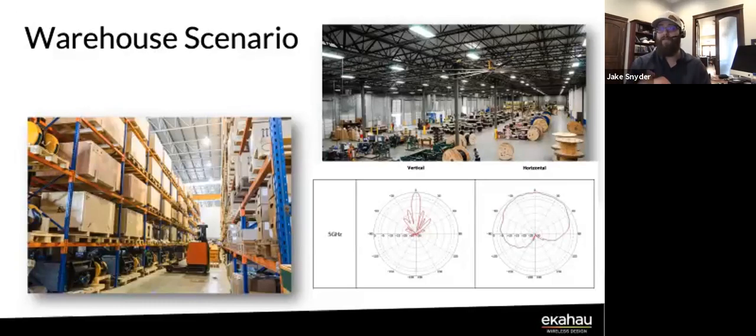And that distance in time, they had a hard time differentiating between what was the original signal and what became basically destructive interference. So when we talk about omnis and spraying RF in all directions, the amount of time it takes for the first signal to the last signal becomes longer and longer, and it starts impacting performance. Directional antennas tighten that up because I'm only sending RF energy in one direction. There's less reflections, less multipath, and consequently that delay spread shrinks to the point where those old clients actually deal well with it.